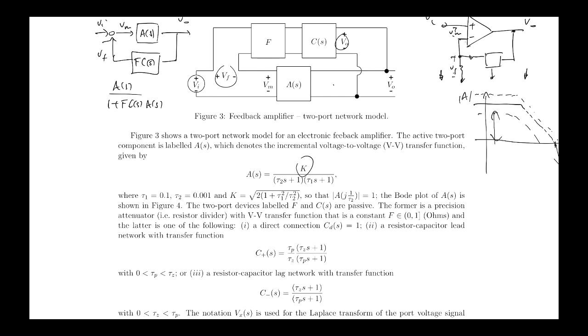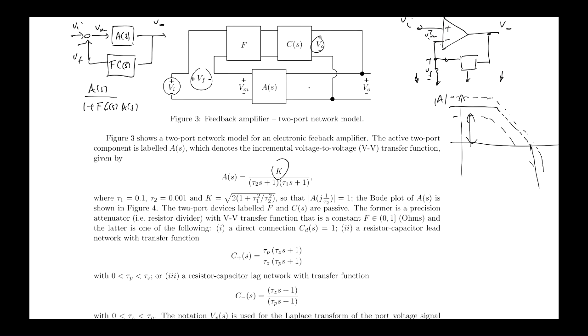Okay, so you know, op-amps are not just constant gain at all frequency, right? The way they relate the output voltage to the voltage across the terminals of the op-amp will change across frequency. And it corresponds to having two stable poles, all right? The point of an op-amp is that it has very high gain at low frequency, all right? But it will roll off at high frequency.